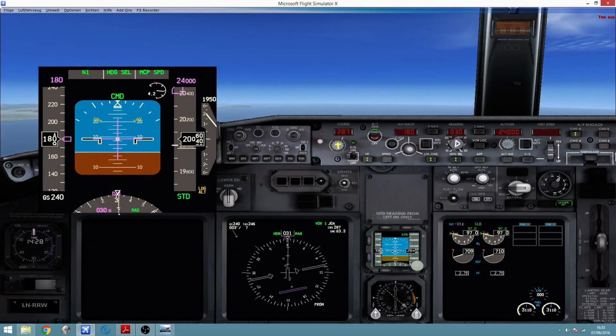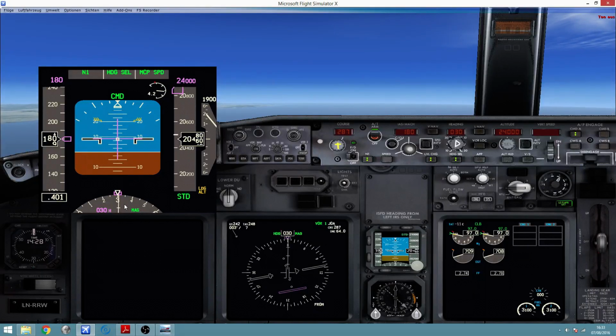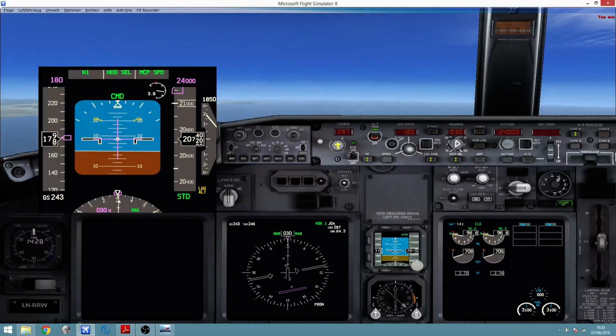And then there is this white cross that indicates the track. This is sort of a small aircraft as seen from above, and it clearly shows, or well, maybe here it's very slight, there is a very slight difference because the wind is not very intense, but the wind is coming from the left, and you can clearly see that the track is to the right of the heading because the aircraft is drifting a little bit to the right. Well, currently there is no wind, so there is no drift at all, but before you could see that.